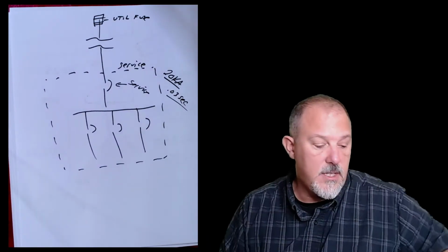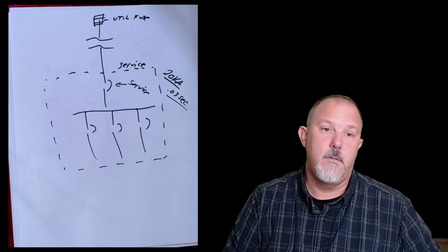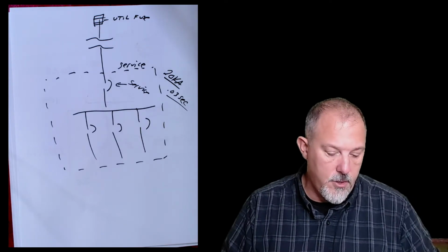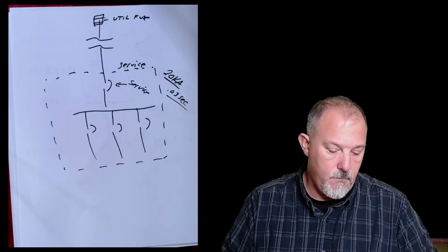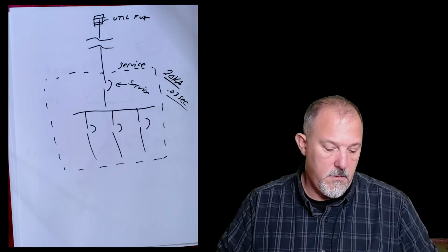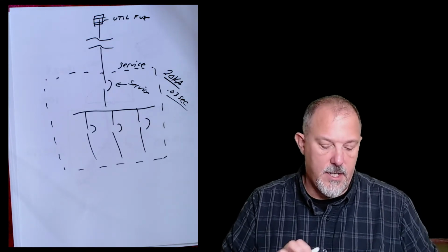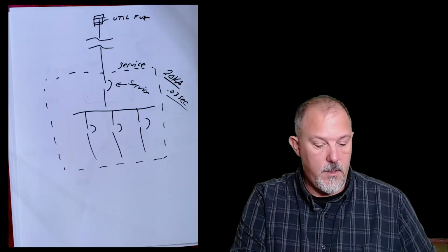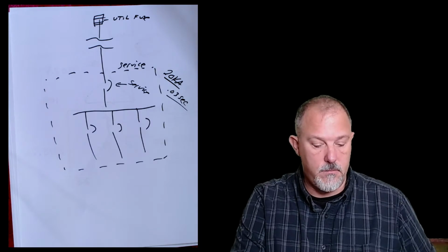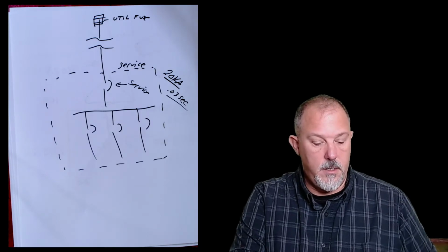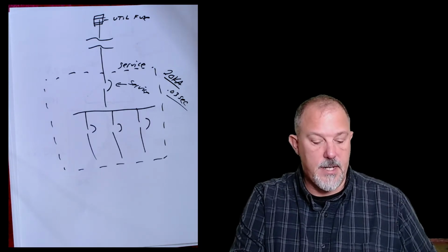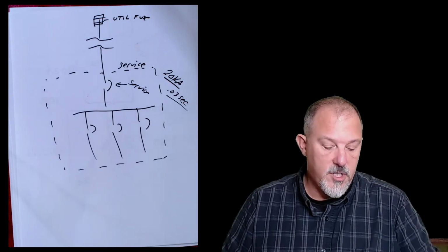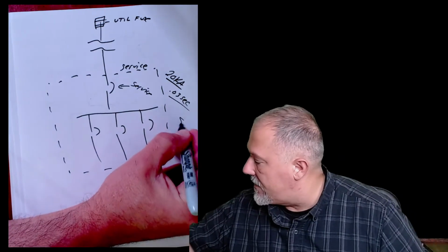If I use the table method for a service entrance panelboard, 20 kA and 0.03 seconds, and say it's 480 volts, I would be in a PPE category 2, which puts me into an 8 cal outfit.